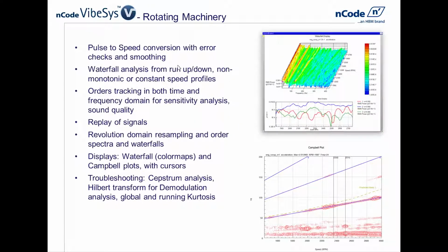Let's start with the first application that I mentioned quickly, rotating machinery analysis. Any rotating machinery such as a thermal engine, electrical engine, a turbine, a gearbox, anything that rotates generates vibrations, and if there is some defect or wear, any kind of fault in there, misalignment, imbalance, things like that, they have their specific signature. So with the modules, part of the rotating machinery palettes that we're going to see in a minute in VibeSys, we can easily